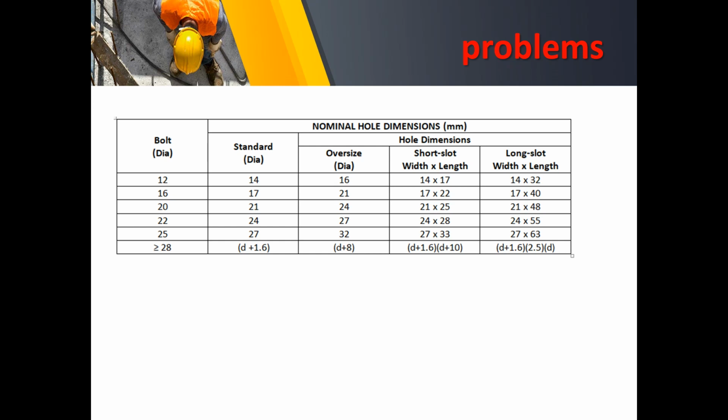In here, I would like to show you this nominal hole dimension table for bolts in SI units. Of course, what we did last time is to add 1/8 to our diameter. In some books, we can find that the calculation is based on the standard diameter.